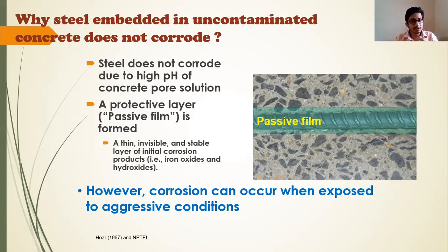There is a particular reason. There are two reasons primarily why we are using steel in concrete. The first reason is that the coefficient of thermal expansion of both concrete and steel is the same. You all know that the reaction in concrete is a hydration reaction which evolves heat. When it evolves heat, in a mass concreting system, the reinforcing in the core of concrete may expand due to this heat.